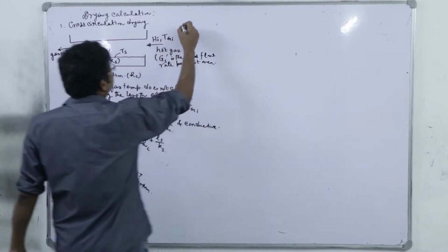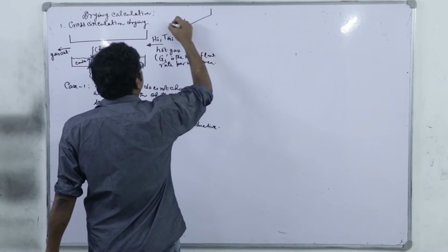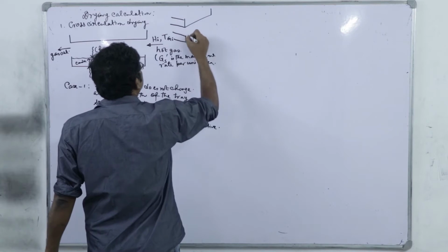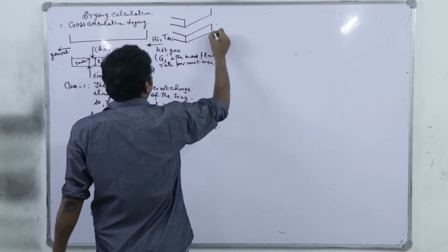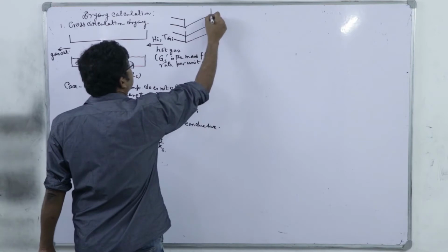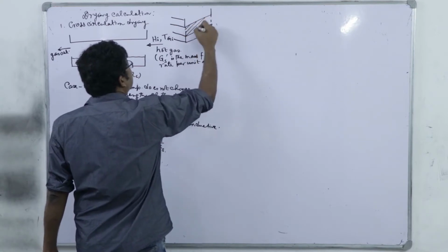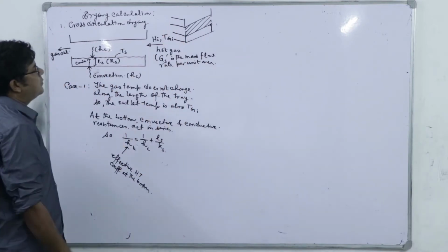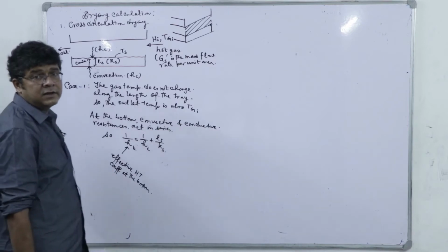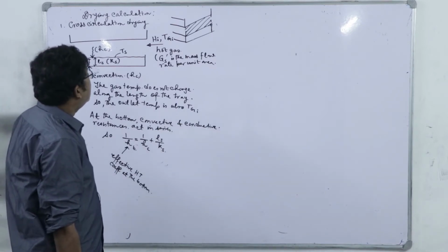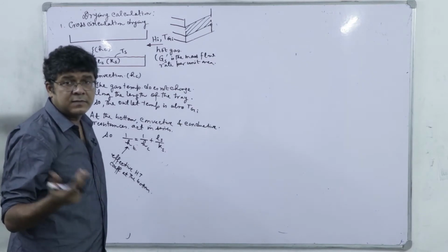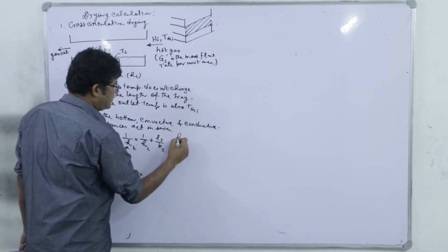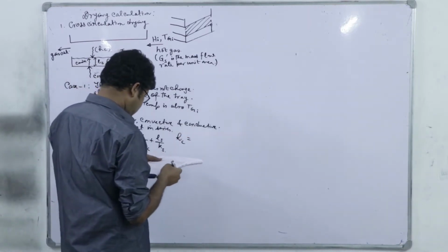The tray in an isometric view looks like this. So, the area we are talking about for gas flow is this area, right? Through this area the gas actually enters and its inlet velocity is perpendicular to this area, and the mass velocity is average velocity multiplied by density. So, that is Gs prime. So, Hc we can find out the coefficient.